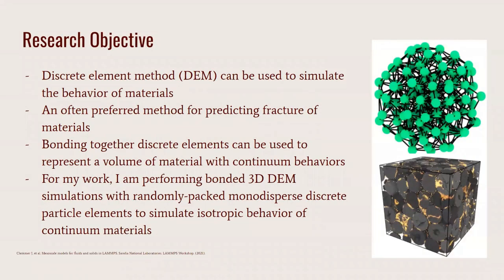Many materials exhibit isotropic elastic behavior and under severe stress states may also fracture. DEM is a great tool for simulating fracture but must also perform well when predicting isotropic elastic material behavior. Bonded particle modeling uses a discrete element method, DEM, where particles that represent a coarse-grained volume of material are bonded together in a network to simulate continuum material behaviors. Randomly packed discrete particle elements are preferred over lattice-placed discrete particle elements for their improved geometrical isotropy.